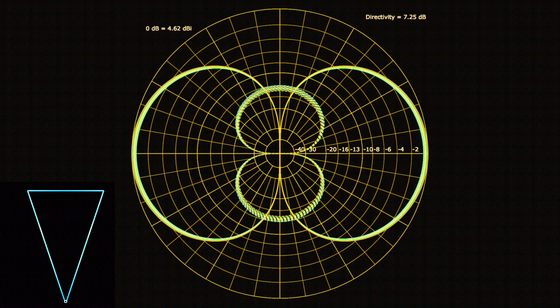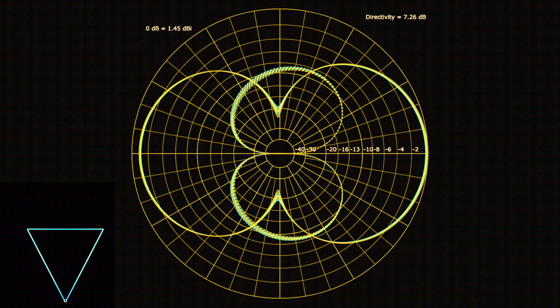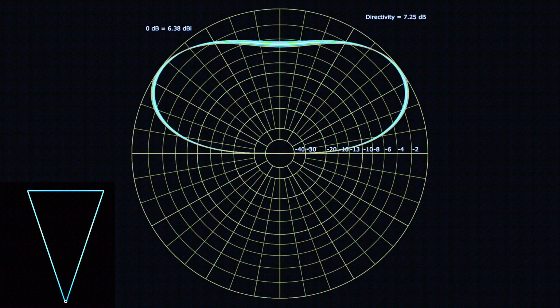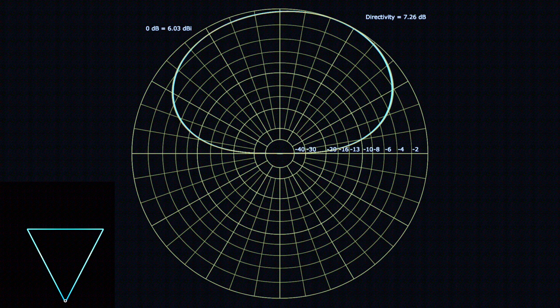The vertical polarization seems stronger in comparison only. The absolute value is also lower. The antenna elevation diagram, also known as vertical radiation pattern, is showing that the tilted antenna radiates more energy to the sky in comparison.